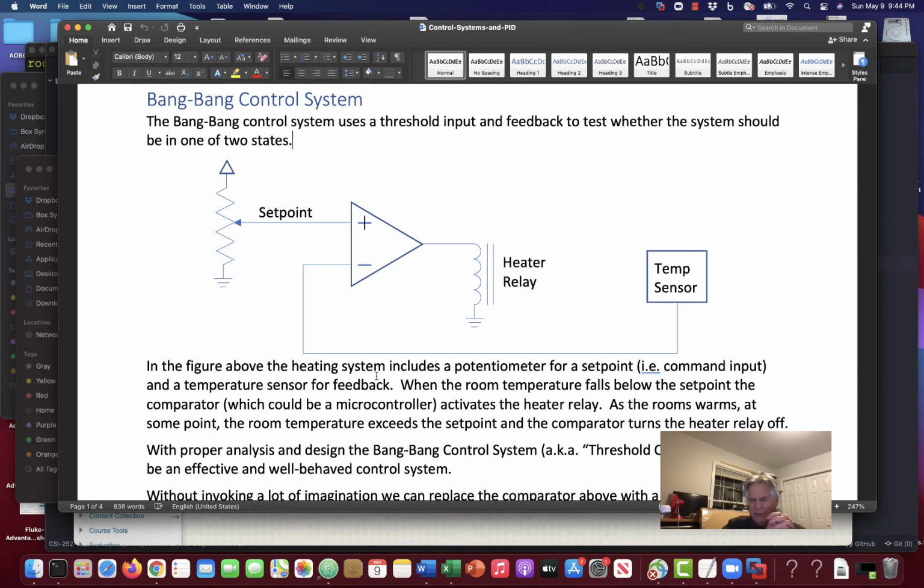Because there's three resistors of equal value, as a voltage divider will create two junction points there, one at 2/3 of voltage, one at 1/3. And you can create a system using the flip-flop in the 555 and those two thresholds. You can create a system that has a third of the supply voltage of hysteresis.